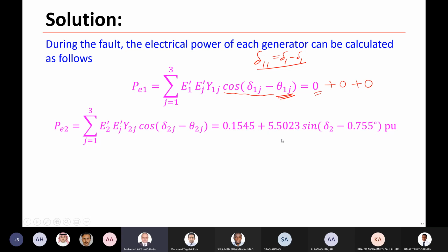It's very interesting to have this part. Now we used to have PE equal to Pmax sine delta. We used to have this formula. But now we have a real part here. You have here a part which is constant, and you have Pmax sine delta, where delta is delta minus theta or delta minus gamma.